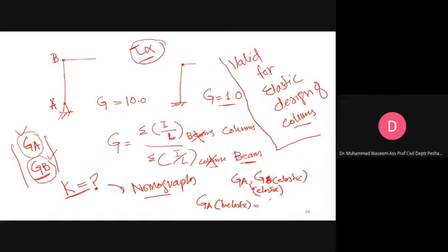K inelastic is G elastic multiplied by tau alpha. This factor you can calculate, or you can use a table in the manual, and that table is Table 4-21. Analytically you can calculate this tau alpha from the ratio of critical stresses: the inelastic critical stress by the critical stress elastic.